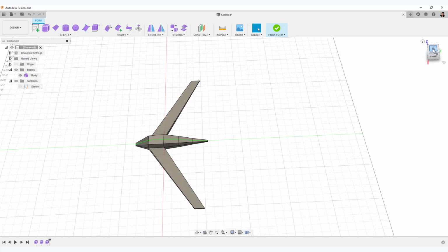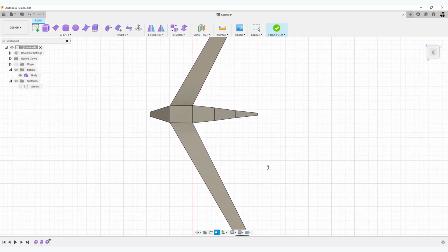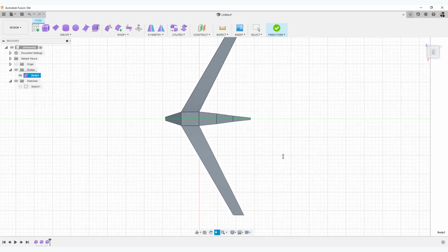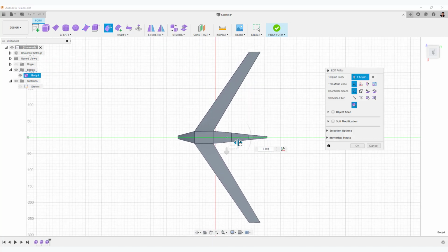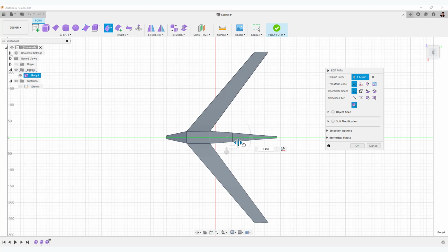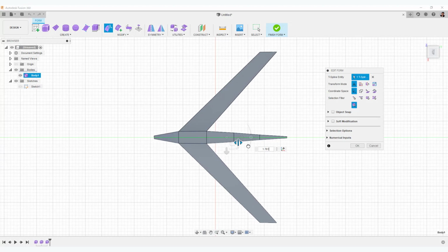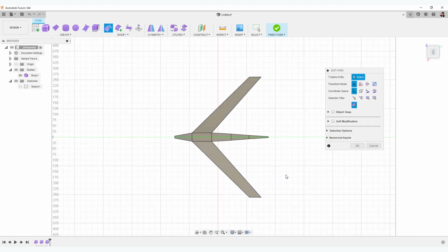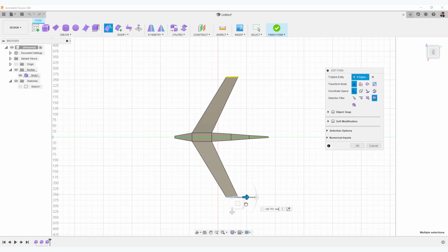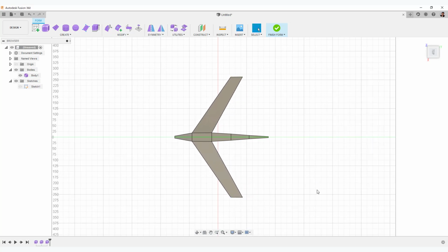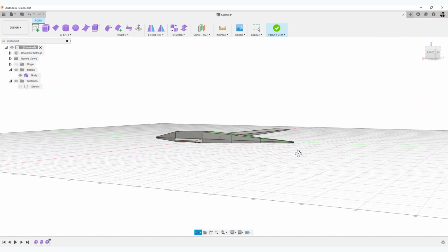The overall proportions are not good, so adjust them by scale. Pick an object and right-click to select Edit Form. Select the left and right scale to adjust the length first. Then select this to readjust the angle of the main wing. The good thing about form modeling is that you can freely adjust the proportions like this.